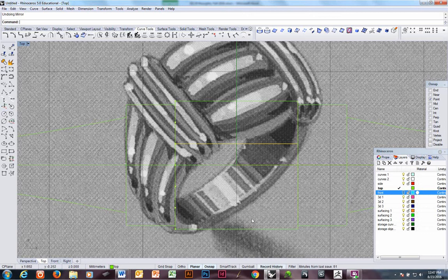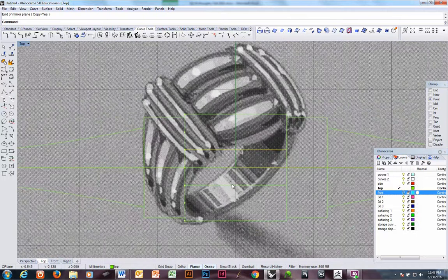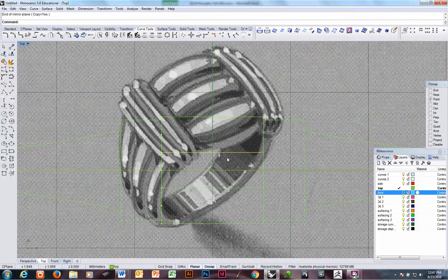I have history recorded. Remember, mirror is F2 on our shortcuts, so I just hit F2. Start of mirror plane, F4. I could have just typed in 0 also, but F4 is 0 on our shortcuts. So I just hit F2, F4, and then hold my mouse out to the side with Shift key to get what I want. Okay, that's why you don't hear much. You hear click, click. But I say mirror, and I figure we all know what that is by now.